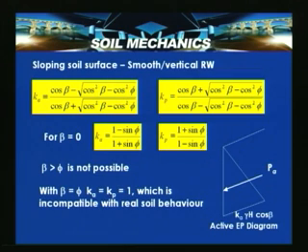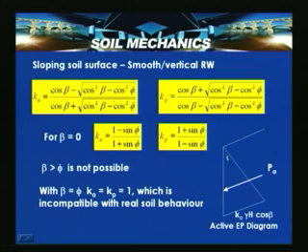Suppose now you have a case where there is a vertical wall of height 8 meters, and the slope inclination of the fill behind the wall is, say, 20 degrees, that is beta is equal to 20 degrees, and the soil has a unit weight gamma. Then you can determine the active thrust like this. The condition is that the wall is smooth, that is the Rankine case.